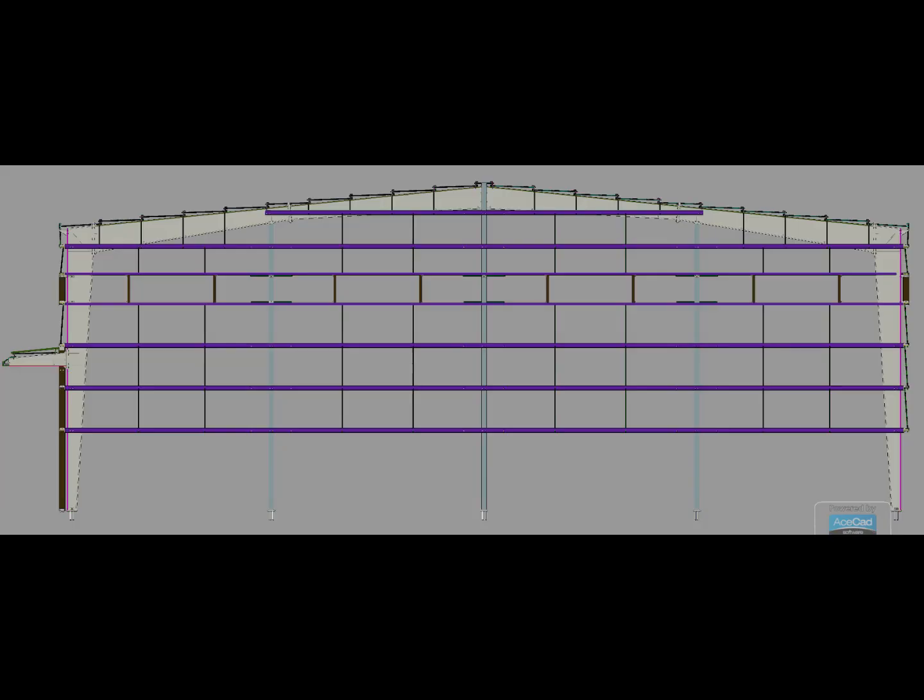This end wall elevation is especially useful for detailers and draftsmen. When preparing fabrication drawings or 3D models, we need to know not only that a sag rod exists, but also where it is positioned within the framing system. The elevation helps us understand its location vertically. The plan helps us understand its location horizontally. And the 3D model helps us understand how the member physically fits into the complete structure. When these three views are studied together, the actual arrangement becomes much clearer.